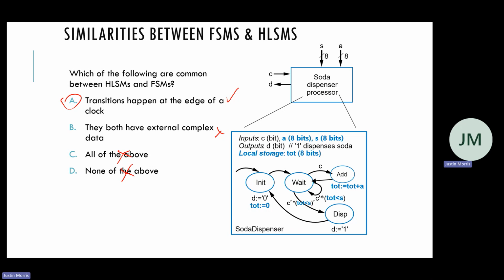It's just a reminder that we're still using the same underlying hardware. It's going to be flip-flops as our storage. And we're still going to use digital logic equations and circuits to calculate what to do next. But now, instead of just using K-maps, we'll also be using digital logic components in order to calculate things like using an adder to add the total, or using comparisons in order to do this transition properly.